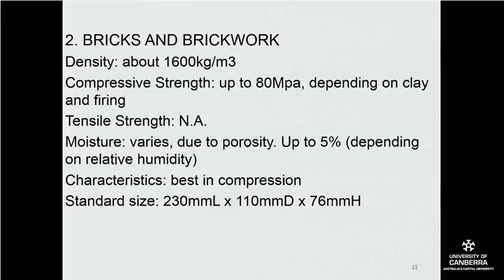The firing or the cooking of it turns it from a plastic, malleable clay into a brick, which is very hard and has a different structure and is completely unelastic and quite brittle. No one bothers with testing the tensile strength of brick because it doesn't have any. Well, not to say it doesn't have any, but it's very limited. Brick is porous, so cooked clay is porous, same as stone, and it's best in compression.